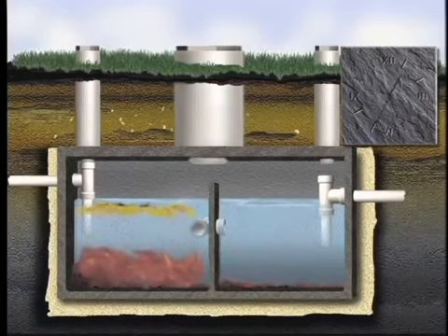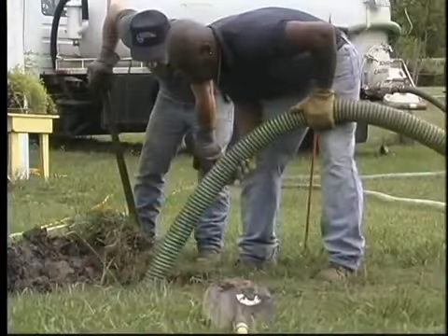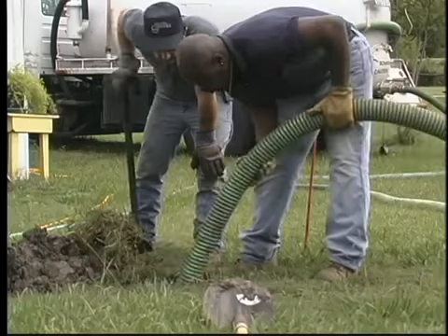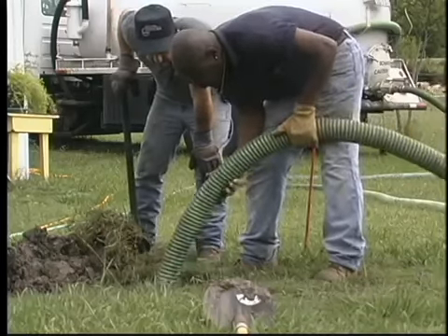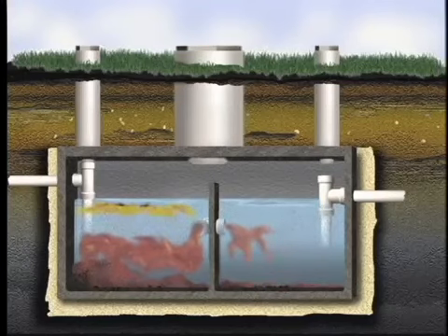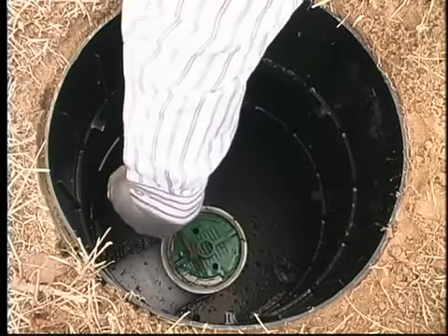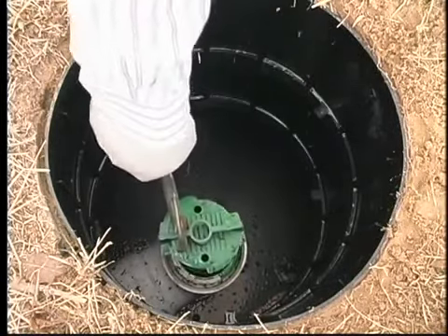As much as 50% of these solids remain in the tank and decompose. The rest accumulates as sludge at the tank bottom and must be removed periodically. Still, the majority of the organic matter, solids, nutrients, and pathogens remain in the wastewater as it leaves the septic tank. An effluent filter is used to assist in removing additional solids from the wastewater.